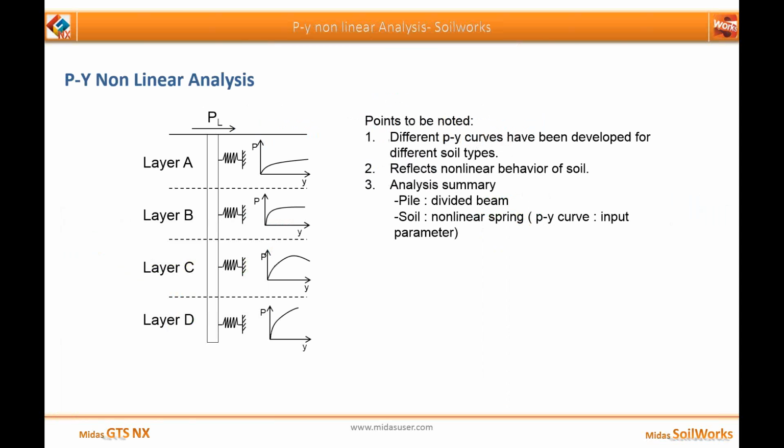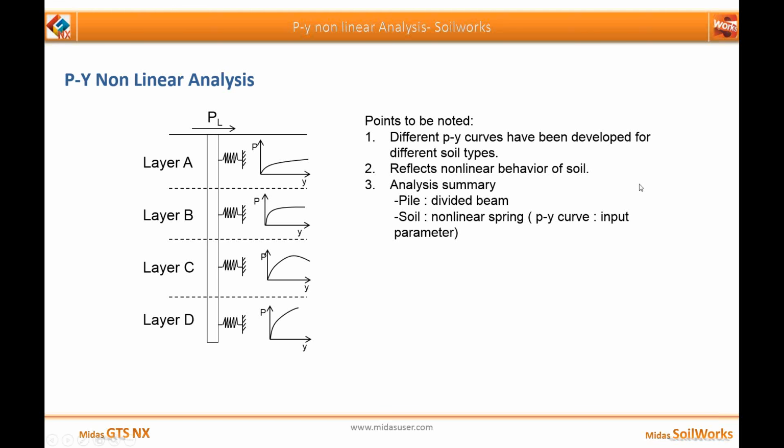So finally I would just like to give a brief introduction of the PY nonlinear analysis. Different PY curves have been developed by different institutes to consider the nonlinear behavior of the soils. In Soilworks one can perform the PY nonlinear analysis. In this, the pile is a divided beam and the soil is defined as a nonlinear spring.